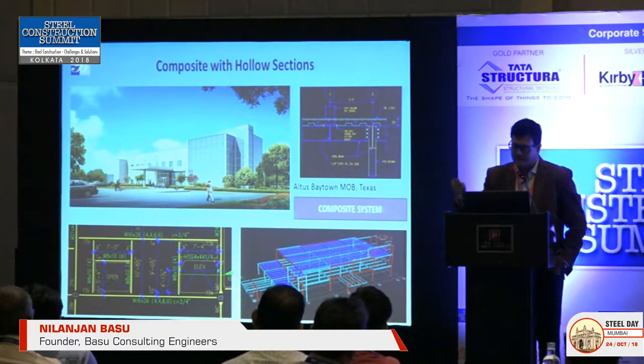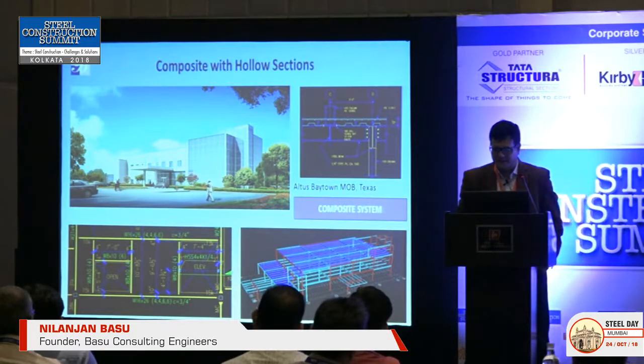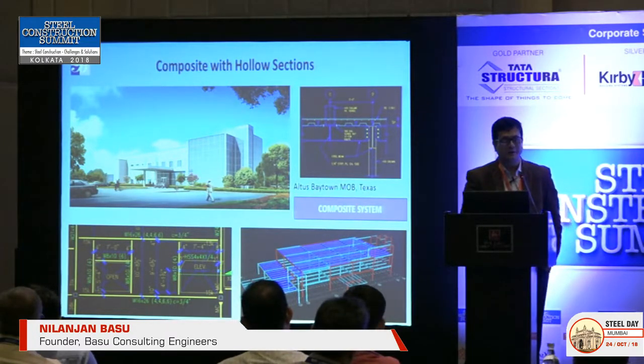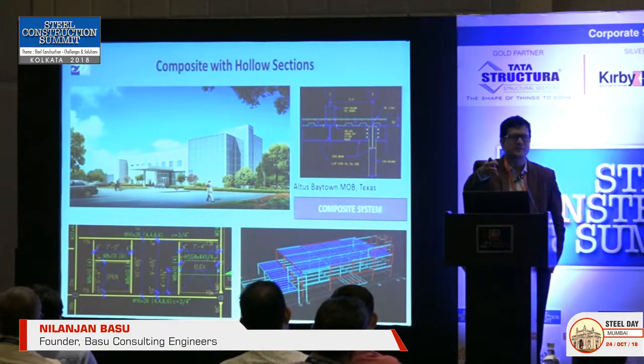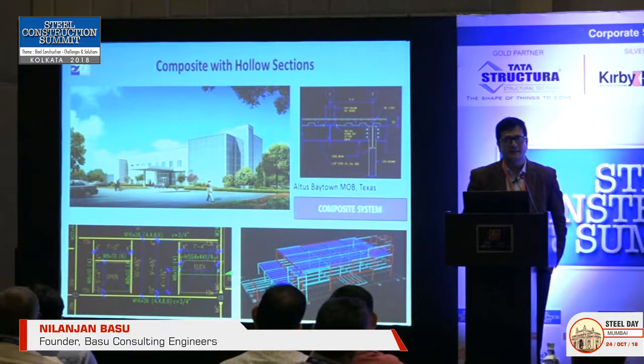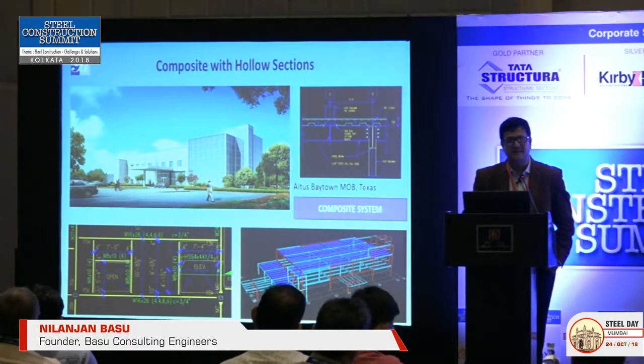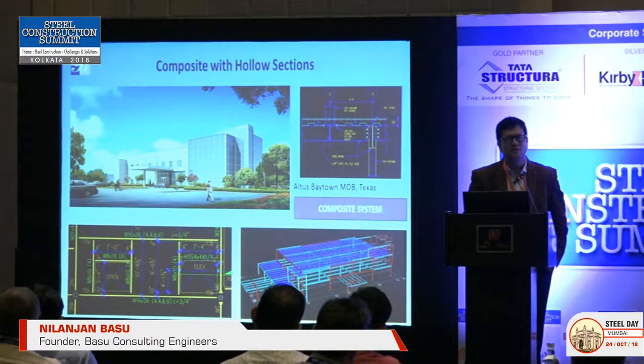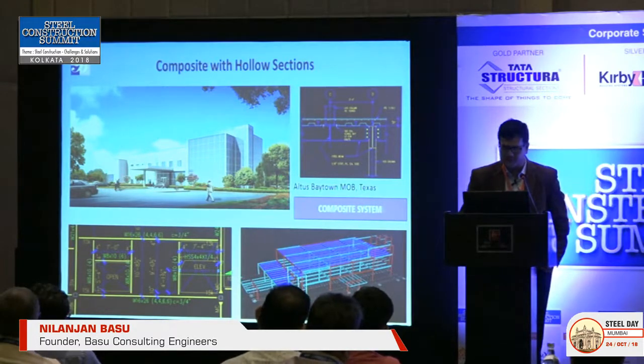On an ideal composite building, I will not go beyond this now. We are using 350 grade of steel in one of the Tata Metalics projects in Kharagpur with one of our clients, Ande. With 350 grade steel, you can have a lot of control over the beam depth, the section usage and economy. So you can go with 350, I would not go beyond 4.25 kg per square feet. That's an effective design of a composite structure. Thank you.